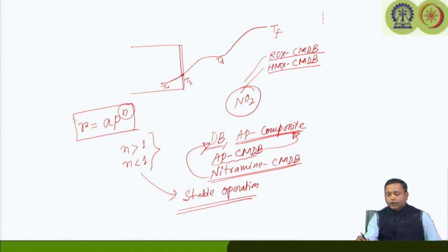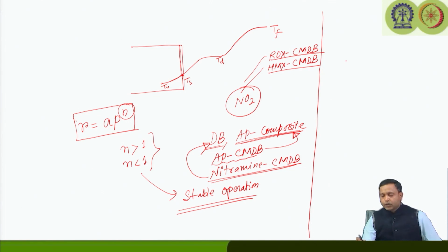In order to understand that, we need to look at how the mass generation is going to take place inside the rocket chamber, and how the mass is leaving the nozzle. If we look at the equations, we may get an idea about how they are related to each other. So, let us look at a typical end burning case, where we can simply draw a typical rocket where the grain is an end burning grain. We have seen that an end burning grain burns this way.